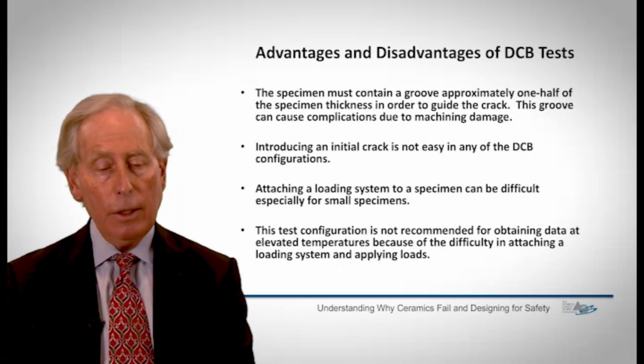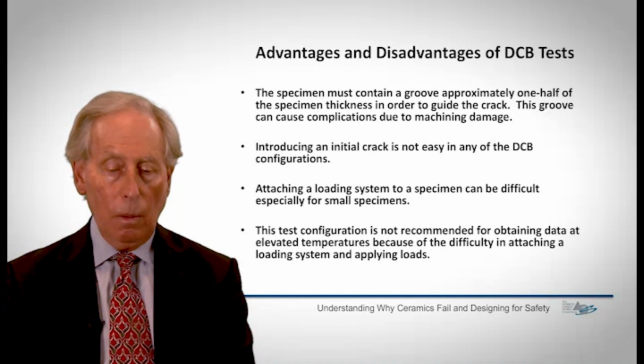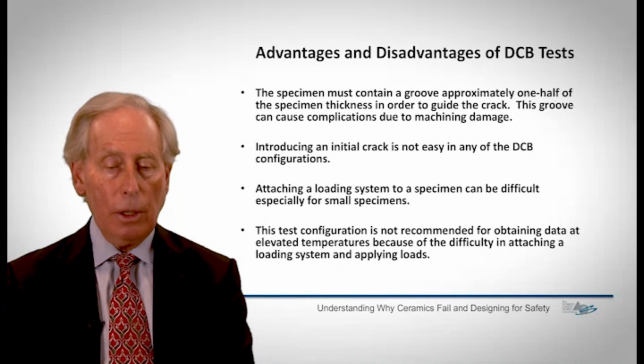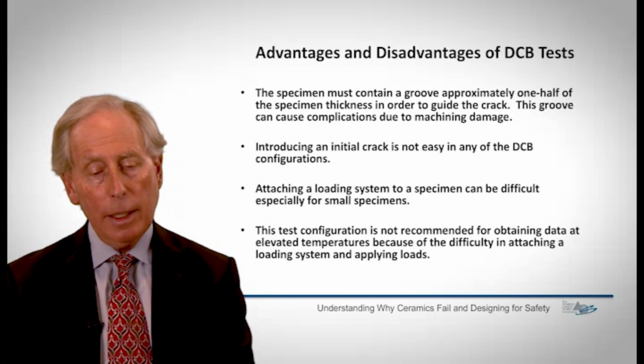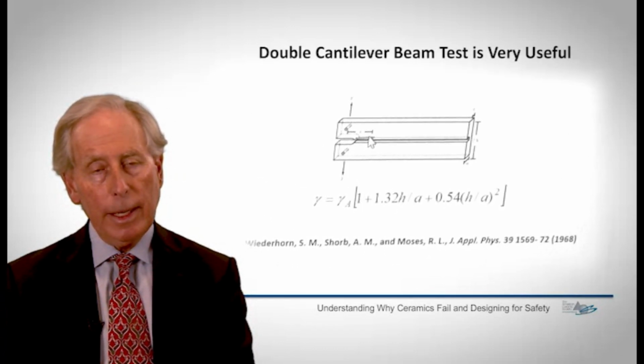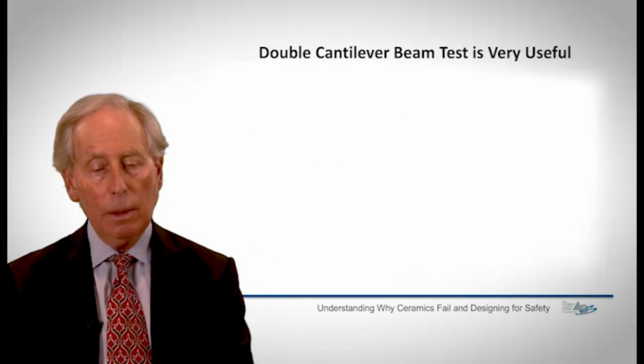In addition, introducing a crack is not easy in any of these configurations. In other words, let's go back and look, and I'll show you a bit why that's true, how one might do it. This is the easiest one. So now I can put a little saw cut in here, but I don't necessarily guarantee myself that there's a crack at the end of that saw cut. And there are lots of little clever ways in which I can get the crack to pop out of that saw cut. None of them are easy. One loses specimens in putting the crack in, etc. So it's possible. It's been done lots of times, but it's not the easiest procedure in the world.